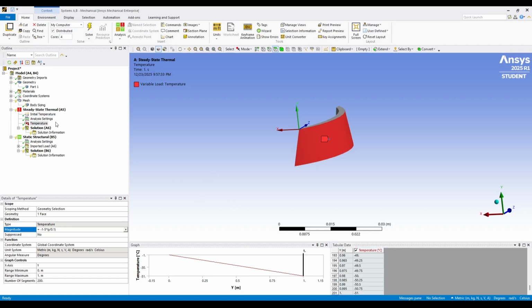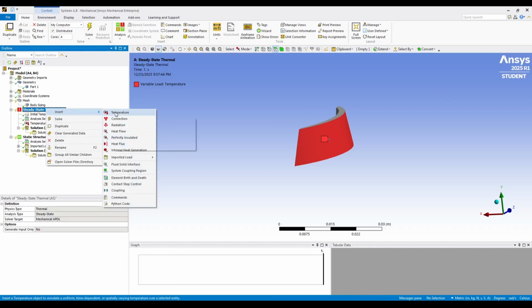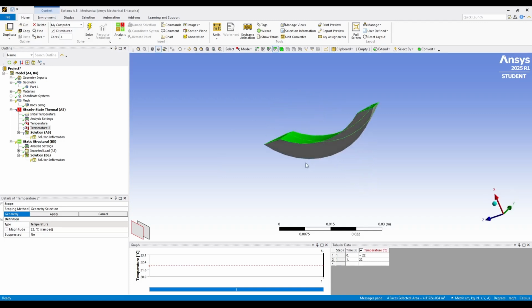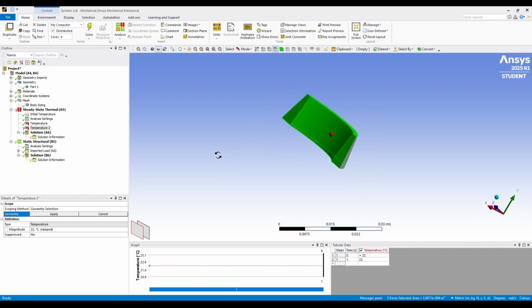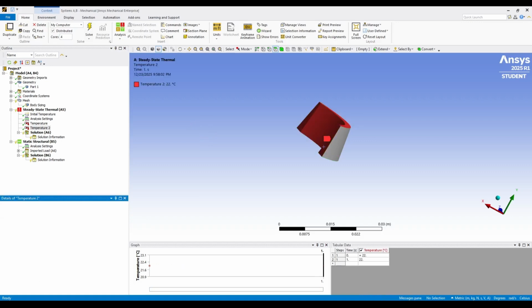In some areas, thermal expansion increases overall stress, while in others, it slightly reduces deformation caused by water pressure, depending on the direction of temperature flow. This combined behavior explains why dams may experience cracking or stress concentration even when mechanical loads remain constant.